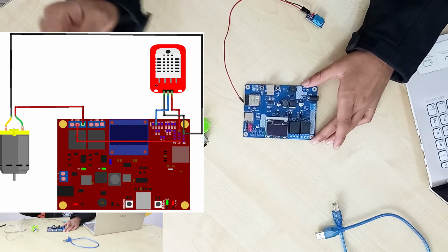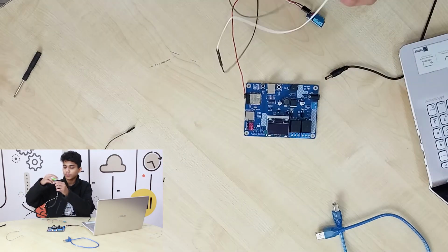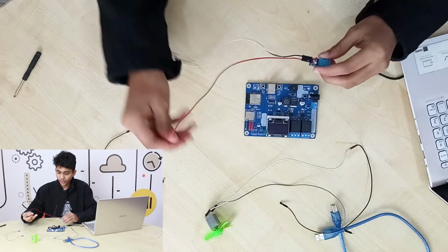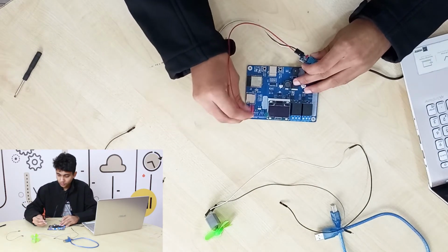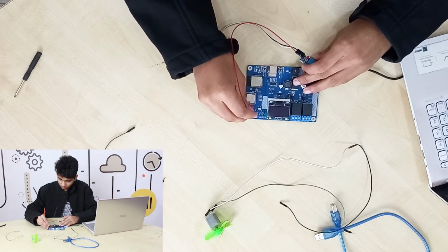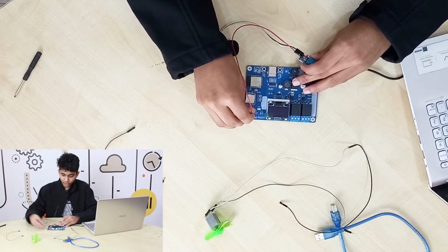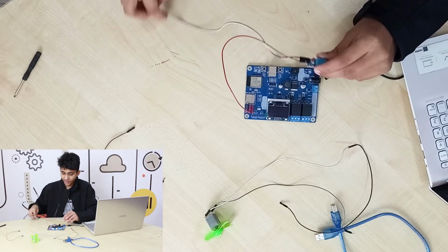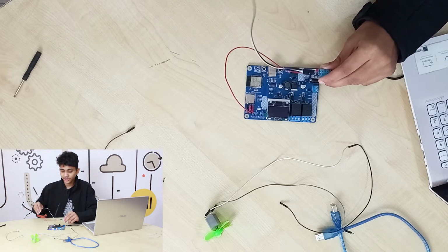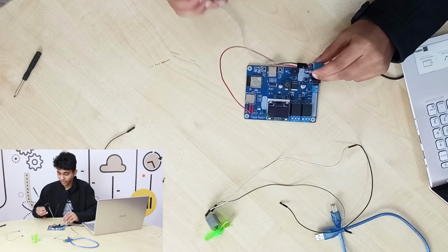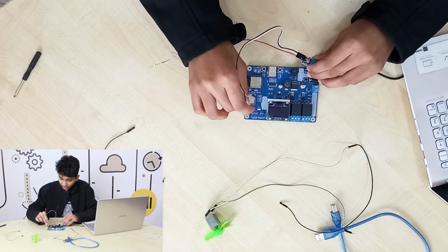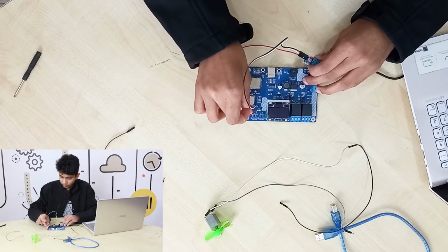And in our code we are going to connect our sensor first. So let's connect our VCC with 5 volts. You can even use 3.3 volts because it doesn't matter for this sensor. But there are some sensors which will burn out when you use 5 volts, so you need to be careful on that.